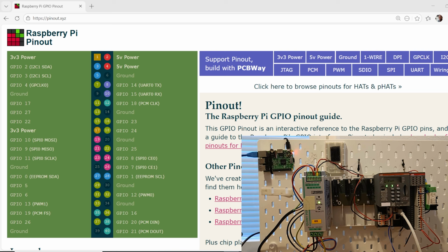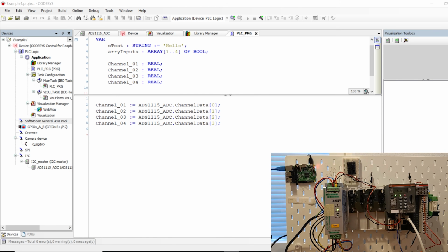If you look at the pinout table for the Raspberry Pi, you have GPIO 14 and 15, and these are designated as UART0 TX and UART0 RX. So these are the serial pins on the GPIO interface. You can either connect via these pins, or you can use the USB interface. We're going to see both approaches, but for this video today, we're going to look at the USB option first, and then later in a separate video, we shall look at how to use the serial pins on the GPIO interface.